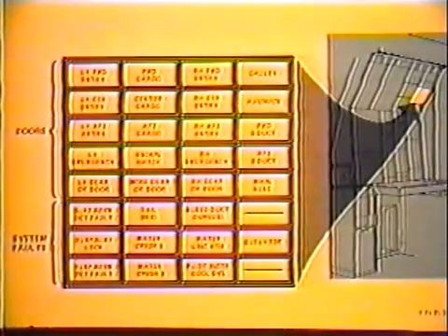The second officer's annunciators are somewhat different from the pilot's in that when activated, these lights illuminate steady and will remain illuminated until the associated door is closed and locked, or the affected system fault is cleared. The upper portion of the second officer's annunciator panel indicates door lock status. The lower portion indicates system faults.